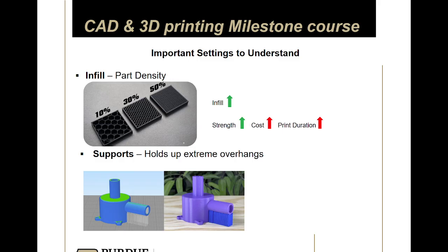On the top here is infill density, which is kind of what I was poking at earlier. Again, parts are not always completely solid in nature, so you can control how dense it is on the inside. I'm passing around 2 samples, one at like 25% infill and one at like 15 or something, so you can see the different mesh densities.